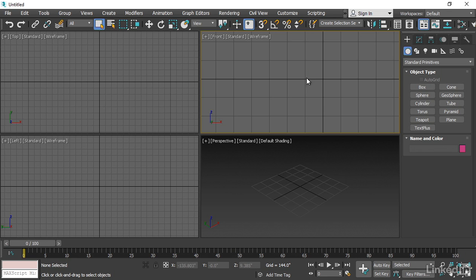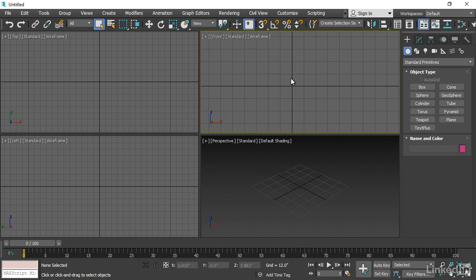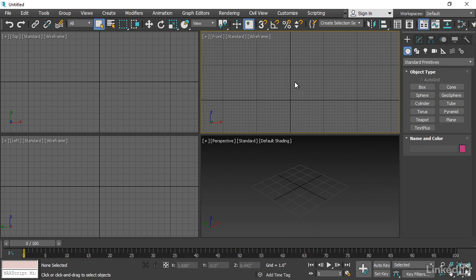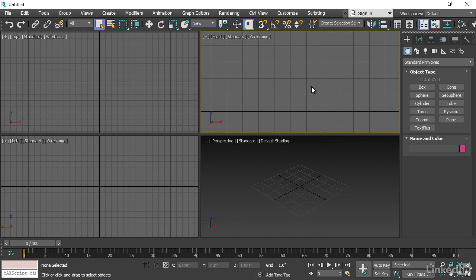And now this distance is not 1 inch, it's not a foot, it's actually 12 feet here. So don't let that bite you, although it's almost certain that it will. The only way around this is to make sure that you've zoomed in all the way. So if I zoom in to a crazy distance here, now I know that's 1 inch. Okay, so that's all of that.